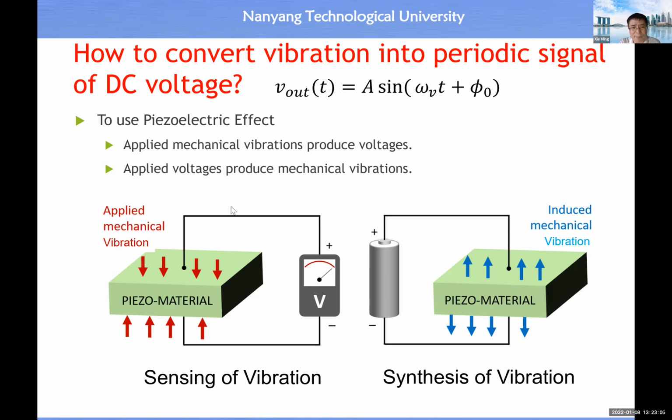The piezoelectric effect allows us to design sensors and also allows us to synthesize vibration. For example, if we have a periodically changing voltage applied to the piezo material, then this piezo material will undergo periodic vibration, all right? At the beginning, we saw the video on how to make use of vibration to design a linear actuator and rotary actuator. So basically we follow this second property of the piezoelectric effect. But here, we just apply the first property of the piezoelectric effect, right?